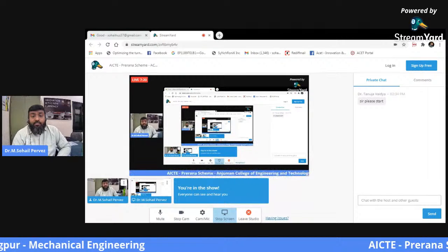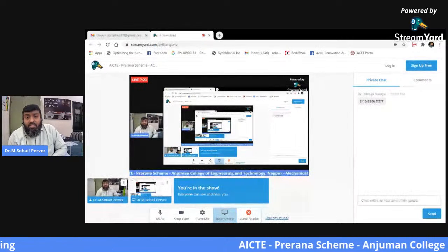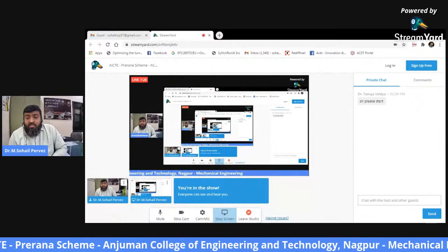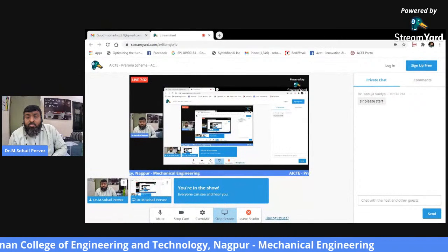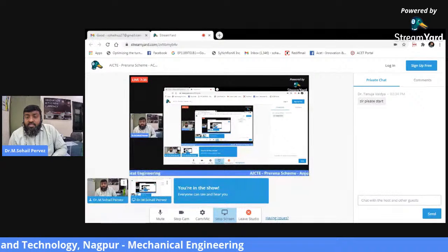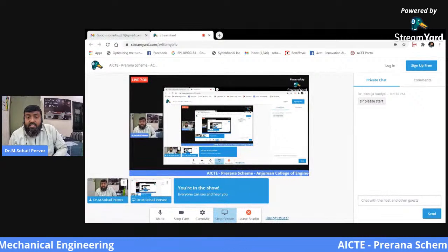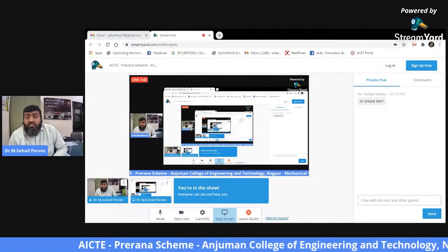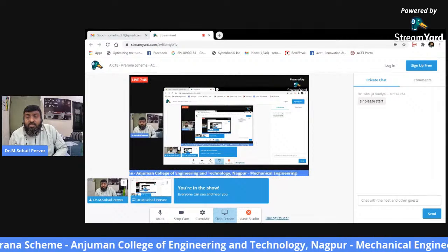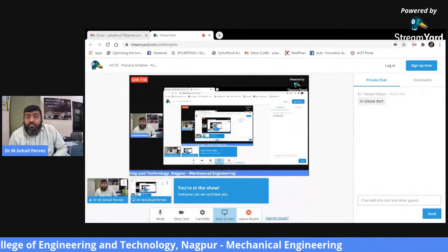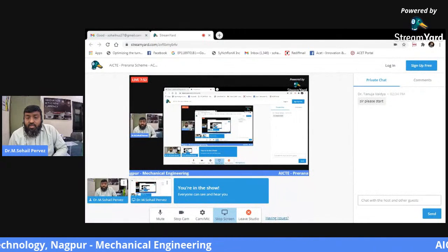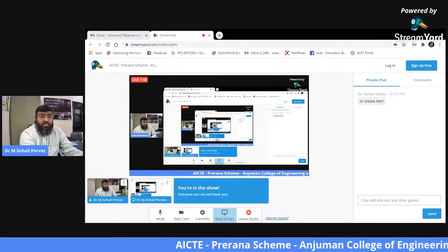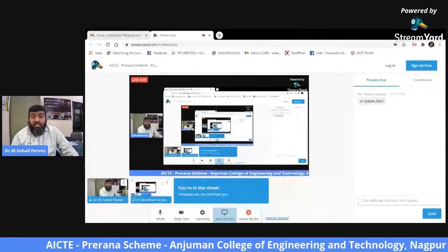Next, again I am using the same equation here. A fillet welded joint is subjected to transverse loading. Both legs of the fillets are 10 mm size, that is S is size of weld, and length of weld along this plate or along this width will be some 30 mm. If allowable shear stress of the weld is also given, then how would you calculate? This is the basic formula I have written here, and based on this formula we can get the answer.